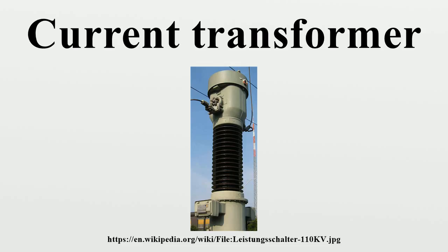The primary winding may be a permanent part of the current transformer, with a heavy copper bar to carry current through the core. Window-type current transformers are also common, which can have circuit cables run through the middle of an opening in the core to provide a single-turn primary winding. To assist accuracy, the primary conductor should be central in the aperture.